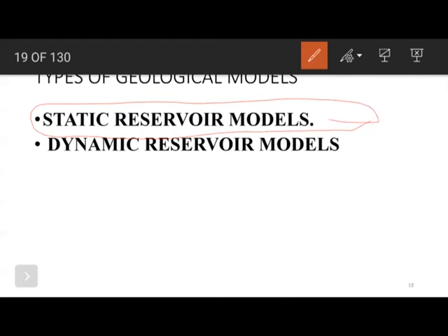From there we will learn some simulation, test different scenarios of production and of enhancing oil production, and place wells in different directions. It will help us decide an optimal location for placing a new well for injection or for production.